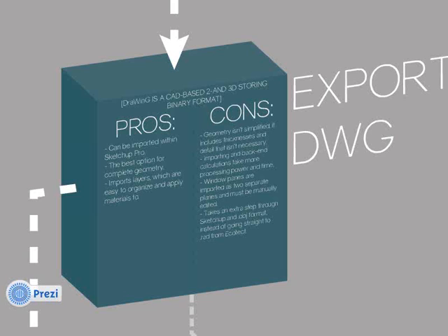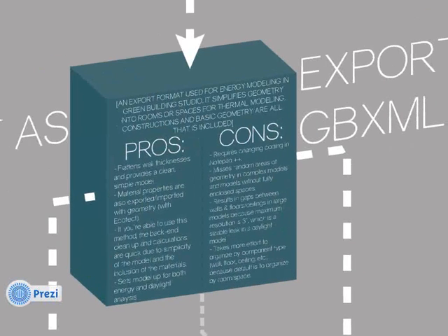So there's a little bit of model prep that goes on if you're going to use the DWG. You can't really just take the file, export it as the DWG, and bring it into the model. It's going to be a little bit too cumbersome that way, so there's a little bit more cleanup on this side. Also, one weird quirk that hasn't been solved yet is that window panes come in as two separate planes, right? They have thickness when you model them in Revit or in CAD 3D, so they come in as two separate planes. You have to make sure you delete one of them so that your window specifications aren't thrown off. That's always something you need to be aware of, and we'll talk a little more about geometry implications down the road.